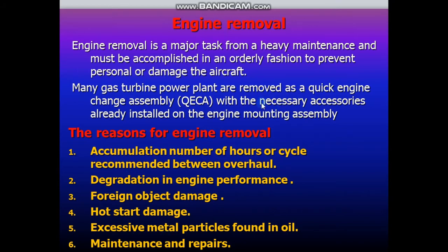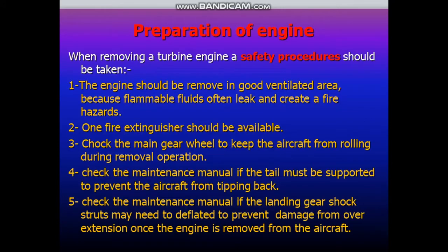Before we remove the engine, we have safety procedures we must follow. The safety procedures to take before removing the turbine engine: the engine should be removed in a well ventilated area. Why? Because flammable fluids often leak and create a fire hazard.